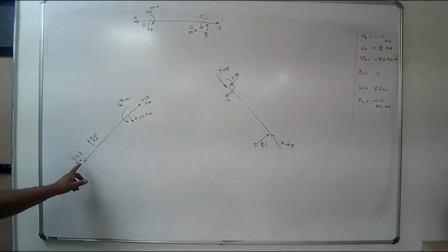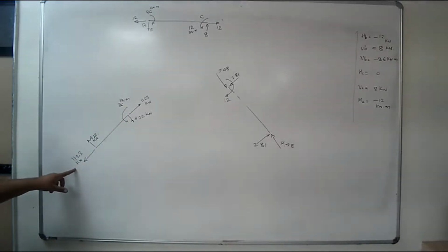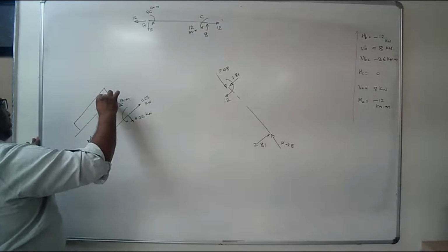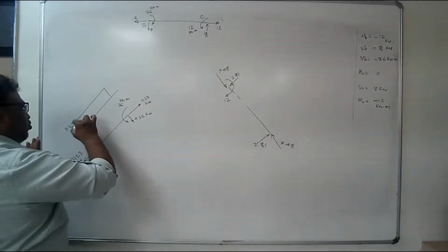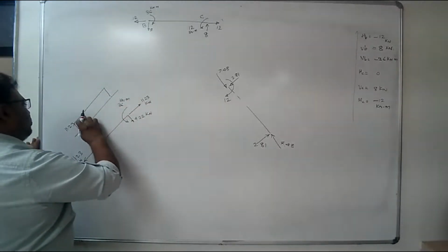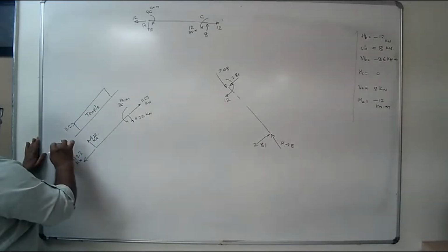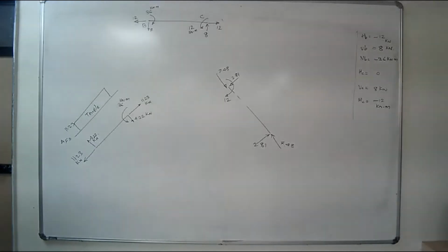What will be the axial force diagram here? This is the axial force which is acting along the axis of the member. It is tensile in nature. So I will sketch here. The magnitude is 11.23 tensile, then from here to here there is nothing, after that it comes back down in the opposite direction. So here this is tensile force. This is the axial force diagram, AFD, tensile in nature.